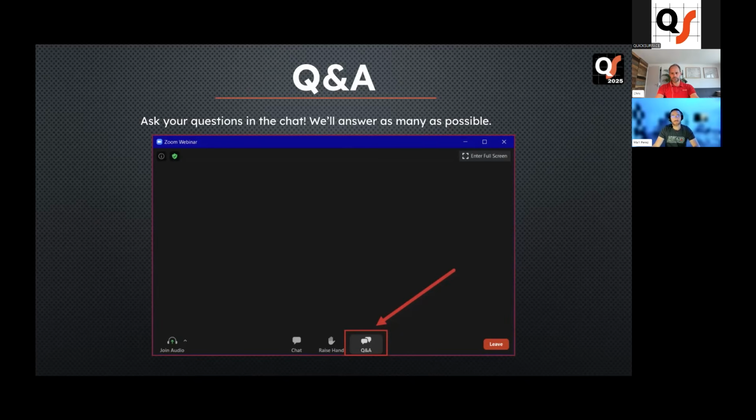So the main, sorry, Chris. The main thing missing in Lite is the ability to use things like Boolean operations, like extruding a sketch and subtracting it from a solid. That's not there. There's also some auto sketch tools, the ability to auto create basically a prismatic sketch from the mesh reference. Those tools are missing from Lite, but you can still extract geometry from it.